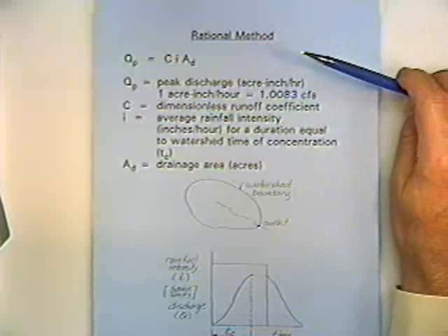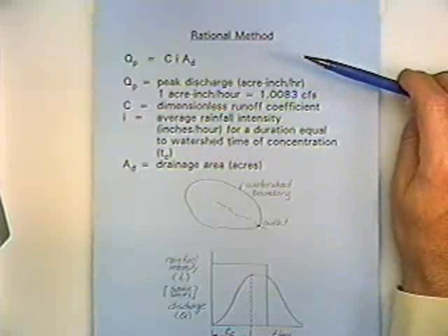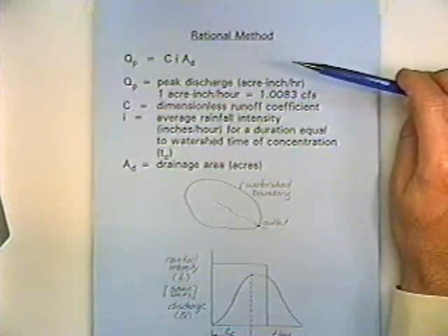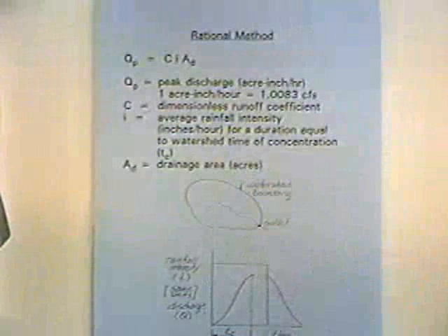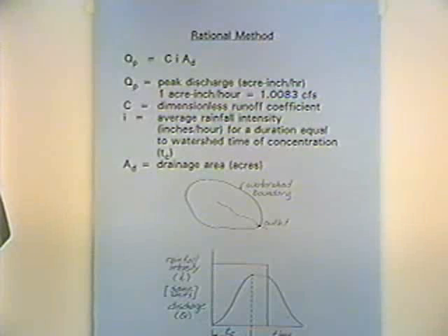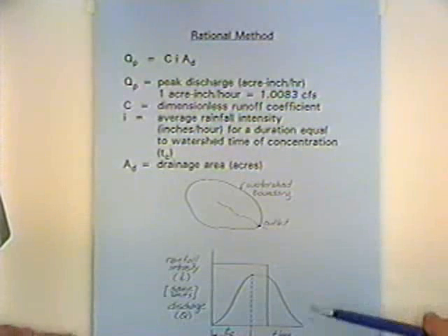The ideal situation would be a drainage inlet in the middle of an airfield, where you know what the watershed area is, and the runoff coefficient's close to 1, but a highly impervious concrete or asphalt. Small watersheds for drainage inlets would be the ideal application of the rational method. But it's used to size culverts and so forth.